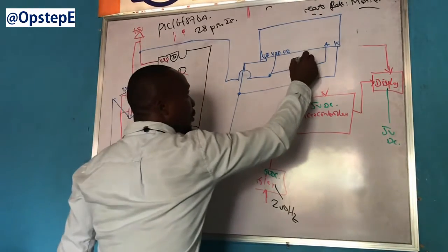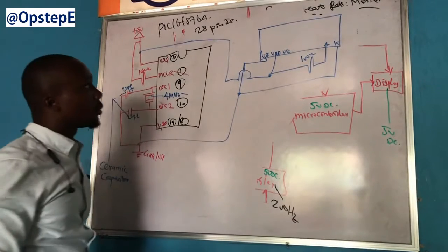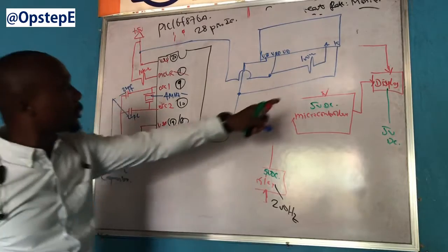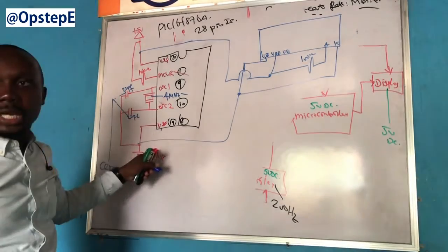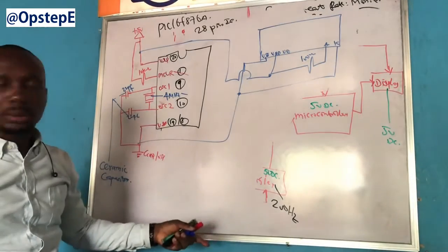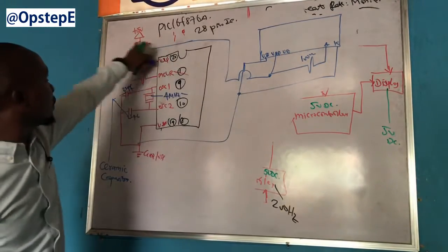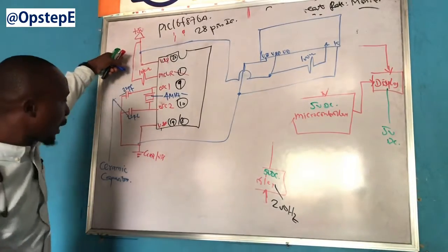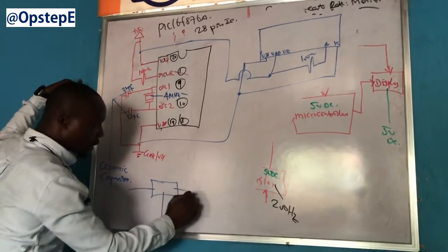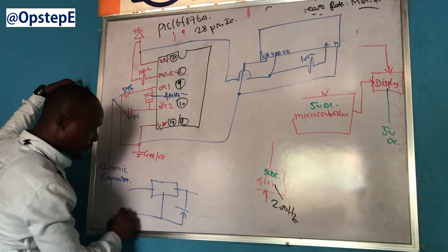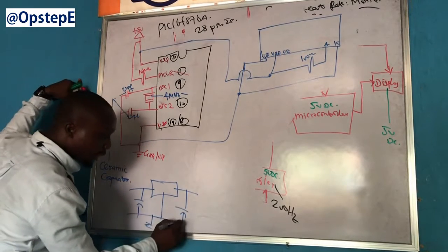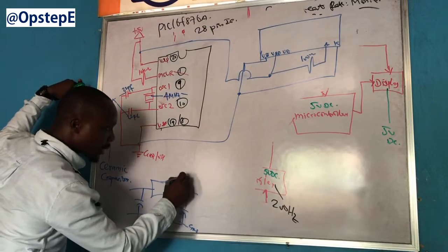Okay. That means the negative is not connected to the capacitor. It's connected directly to the ground. Yes, the cathode is connected directly to ground, while the anode is connected through a resistor to your VDD, positive. But don't forget that at the output of your supply, there's already a capacitor. So this is the ground. This is the VDD.